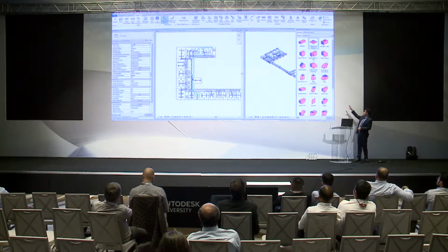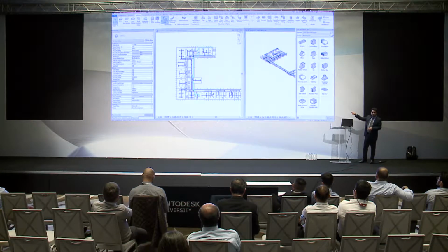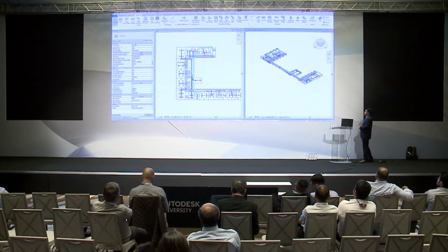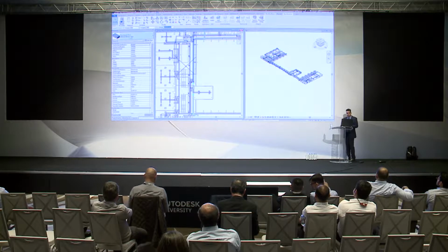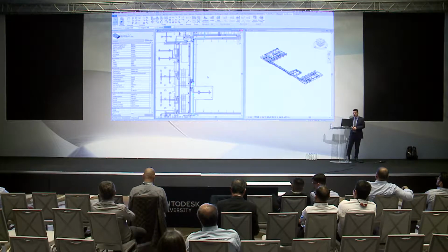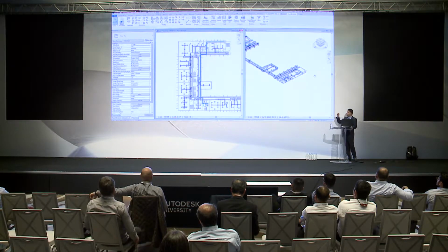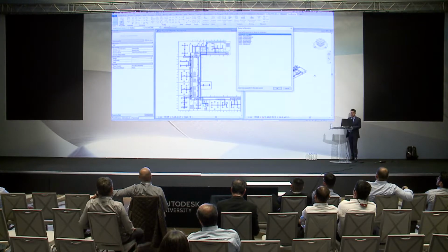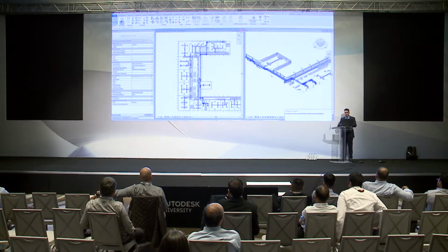All right. Now, there's also a possibility, as I mentioned earlier, if you need to convert an existing Revit model, which is done in Revit or which you receive from a consultant. I have this database, or this content, on the right-hand side, and I'm going to change that Revit content to this particular content. Once I have this content ready, I'm going to select that particular ductwork. I can select the whole ductwork in my entire floor plan, or just one duct, or just one system of ducts. In this case, I selected this one supply duct over here, and I want to convert that. There's something we call Design to Fabricate within Revit MEP. And what's going to happen is, you will not see any changes.